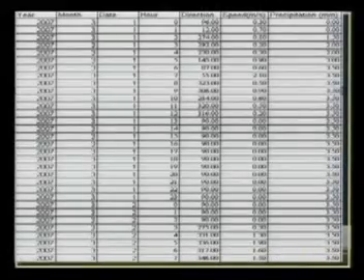Here I am showing you the actual data that has been recorded using the anemometer and the wind vane. In the year 2007, month number 3, which is March, date 1st March, and the hour starting from night time: this is 1 o'clock in the morning, 2 o'clock in the morning. The direction is always measured in degrees. The direction was 96 degrees, 12 degrees, 274 degrees and so on, and the speed was 0.3, 0.7, 0.8.